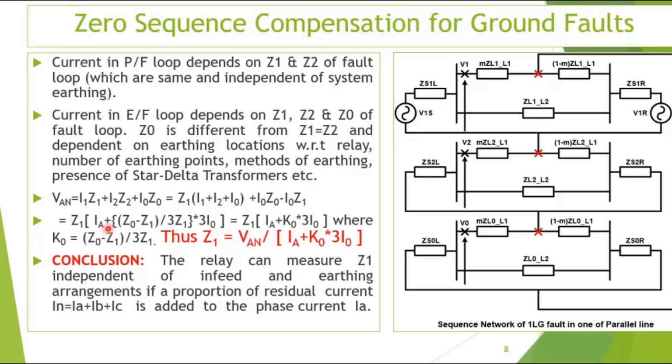That is why the fault has been taken in A phase, mathematically. Now just understand one thing, I have not written over here I1 equal to I2 equal to I0 and this as 3I0. I have written this one as phase current, because at this point I1, I2 and I0 may be equal, may not be equal.